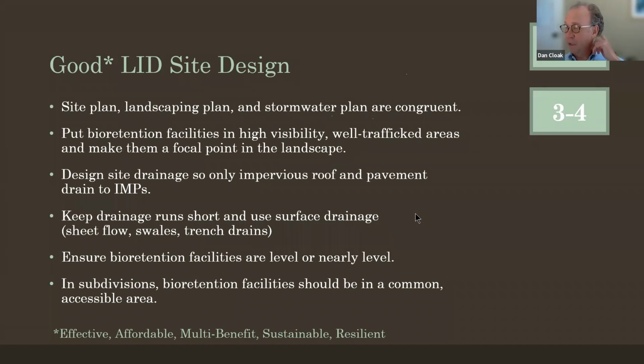So in general, it's just better not to. And I totally understand the difficulty that creates if you're trying to do grading and drainage design, and you're trying to make up some elevation between 2 points, and you have a bioretention facility that is going to be flat. It often pushes you towards needing to do walls that you'd rather not have.